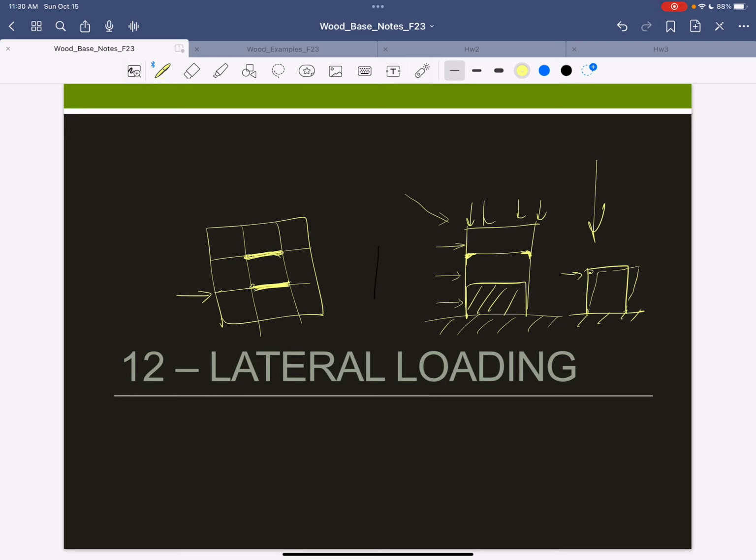This could be a concrete shear wall, it could be a moment frame, or the other choice for steel is a brace frame. So I might have just here, and all of that load has to funnel through the rest of the frames and the floor or the diaphragm to get here. And you make as much of this as you need to take that full lateral force.